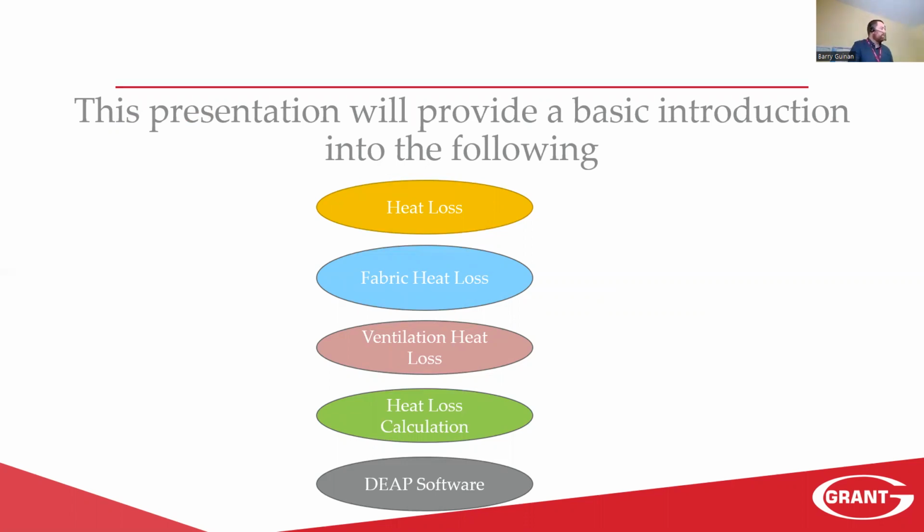So today we're just going to have a brief overview on heat loss, what it entails: fabric heat loss, ventilation heat loss. We will have a look at heat loss calculation, what's involved, what's required, and then we'll also just have a quick look at DEAP Software, what it is, what it does, and the information that's required and what comes out of it.